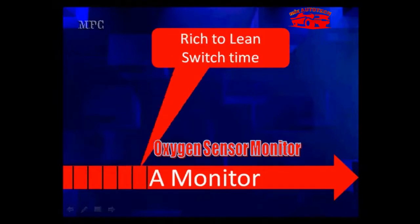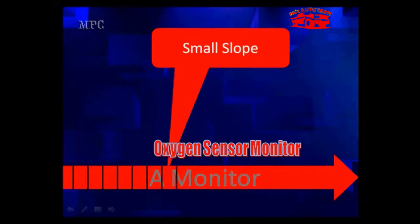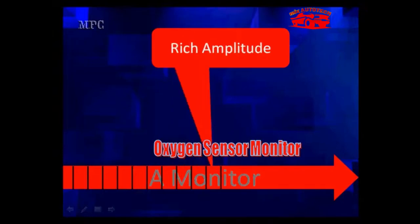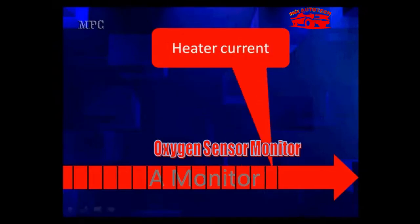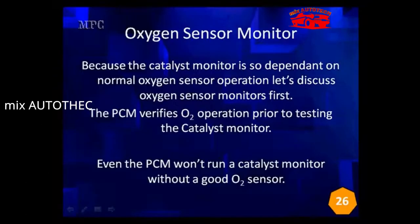Switch points, switch time. We're going to be measuring all that just like we're taking a lab scope. We're going to look at the big slope, which is an oxygen sensor test done by Chrysler, and the small slope, and the half cycle, and the full cycle, the rich amplitude, the lean amplitude, the time to activity to test the heater function itself, as well as heater current. All of that goes in to make up one monitor.